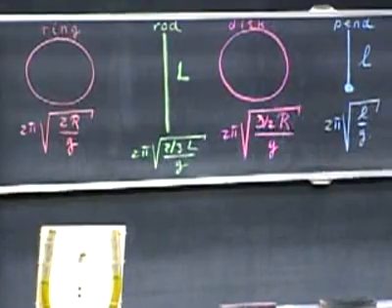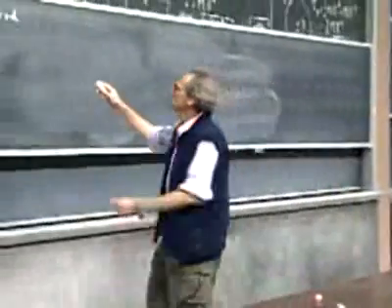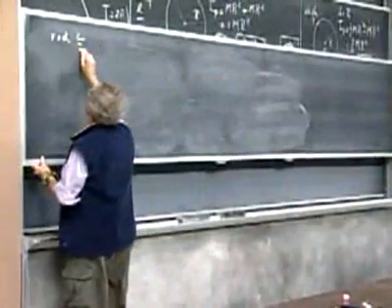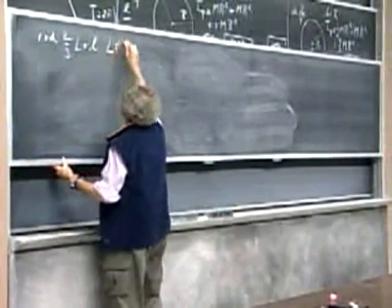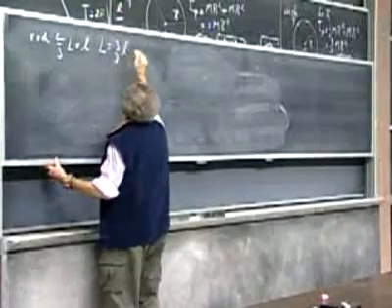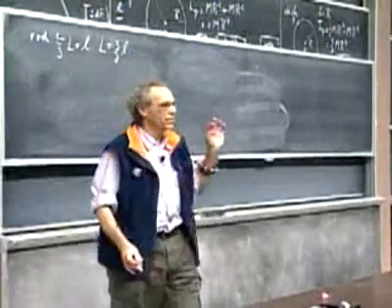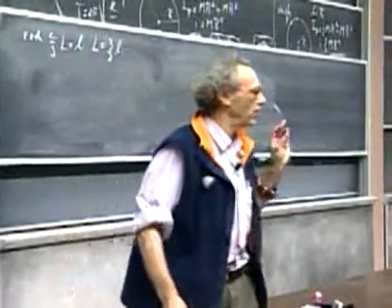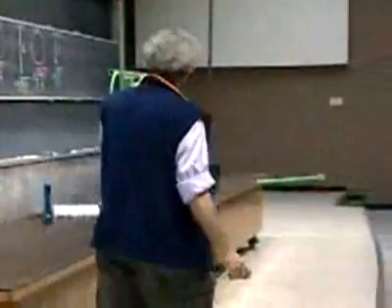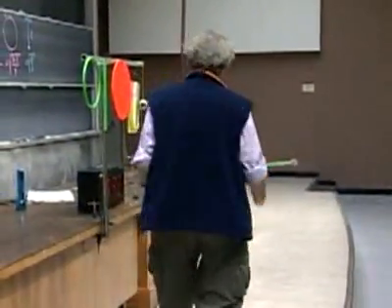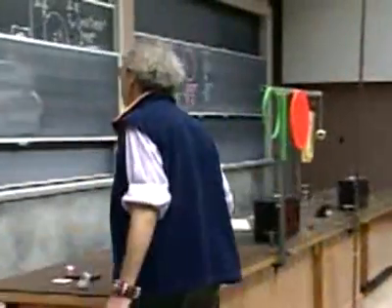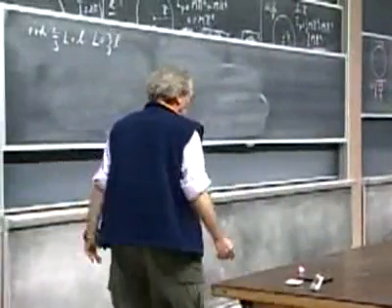So for the rod, 2/3 L equals little l, so capital L is 1.5 little l. It has to be exactly 1.5 times the length of the pendulum. So this length has to be exactly 1.5 times this length to the center of mass, which is the center of that billiard ball. And that's what we tried to the best we could.